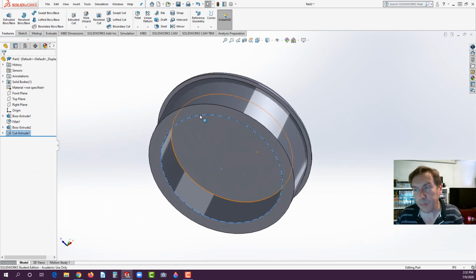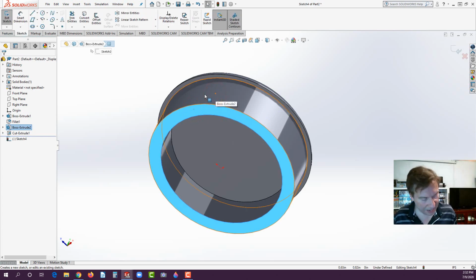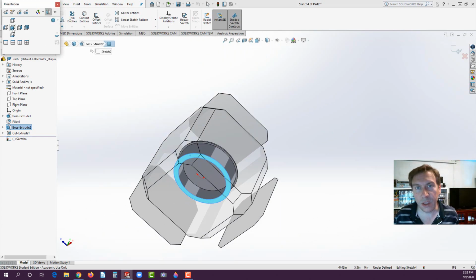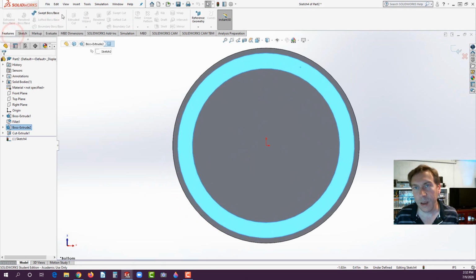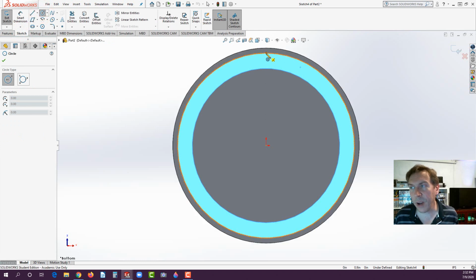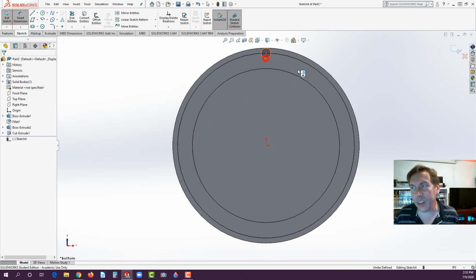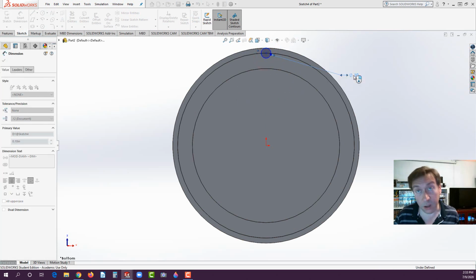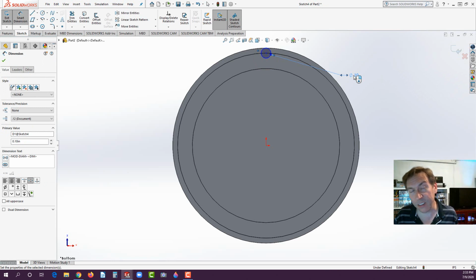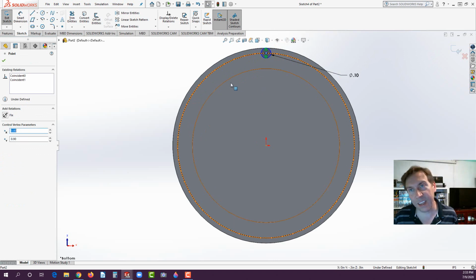Okay, now start a sketch. We're going to start putting the ribs in. Start a sketch on this surface, and I'm going to hit my space bar and go to the bottom. And from here, go to the sketch and the circle tool, and I'm going to get right on this quadrant and click to drag it and attach it there. I'm going to dimension that, even though it is 0.1 automatically because it went tangent to the outer edge and to the quadrants actually. Don't use that. That didn't lock it in. And also you'll notice that this floats. So you want that to lock in too.